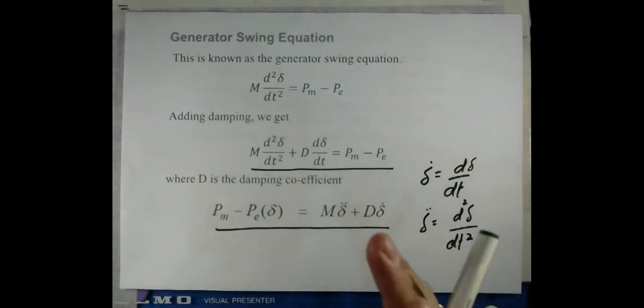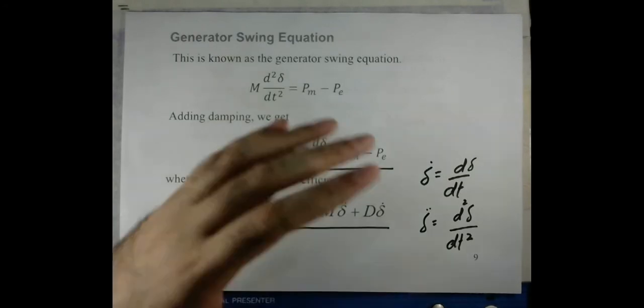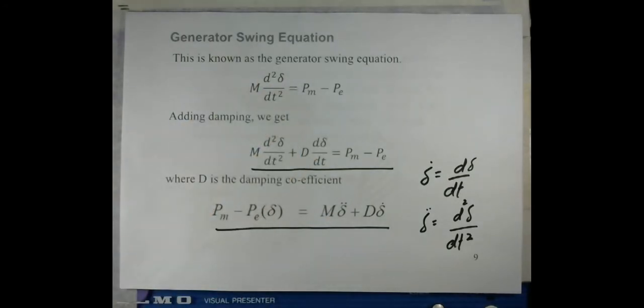So, either we need to solve the swing equation to determine the points of operation, or use the other method that we will discuss today, where we intuitively determine whether the system will remain stable, or it will lose the stability, or let's say the synchronism.